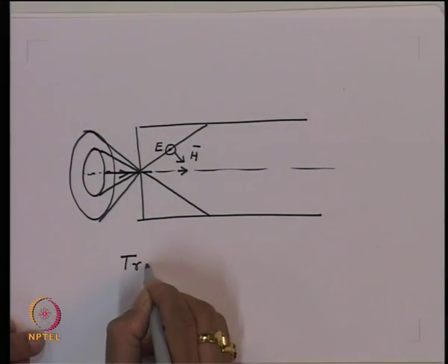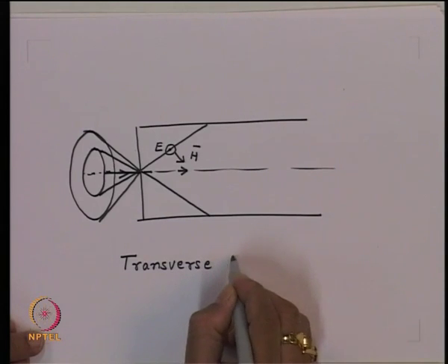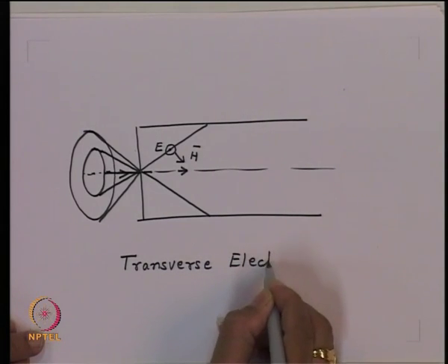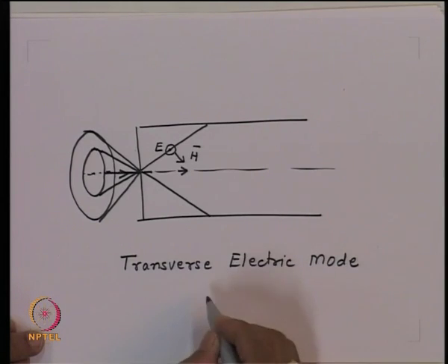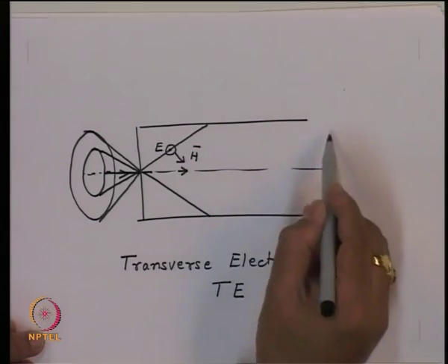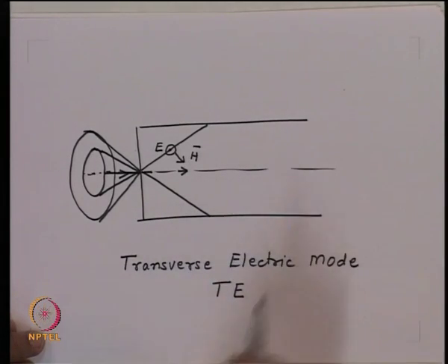So, I have a mode what is called the transverse electric mode, which we denote by TE, and then we put some index for this mode, essentially telling us how many maxima and minima the interference pattern would create inside the core of the optical fiber.